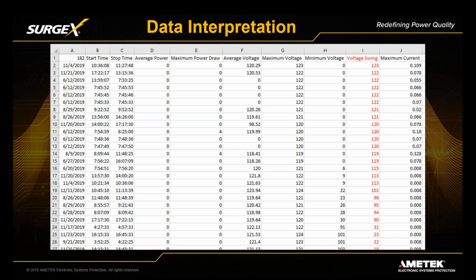And the voltage is the first place where we look, because it is the biggest barometer for your overall AC system's health, which is why, when Vince said earlier, you get a lot of data out of the enVision, even if you don't connect it in line with the load. If you just plug it into a shared outlet and have it record the voltage, that gives you a lot of data. Of course, you get a lot more data if you connect your gear through it, so it actually measures the current and the power draw, and then you can draw even more conclusions. But the voltage itself is a great place to start. Sorry for hijacking you, Vince.